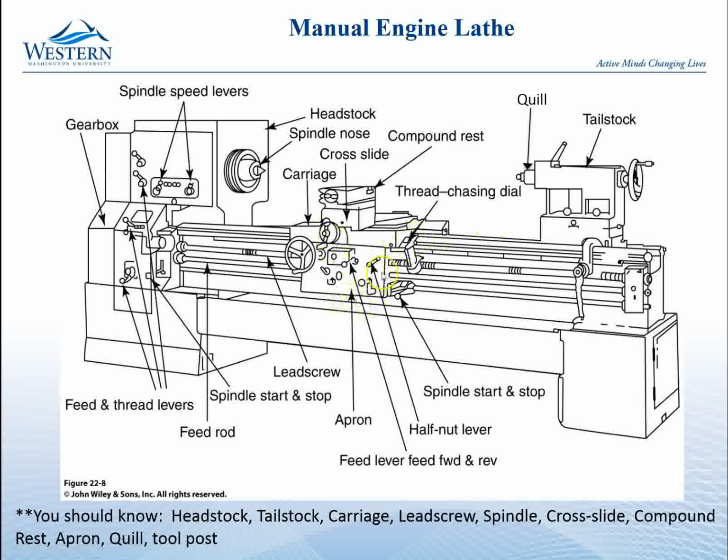Other parts of the machine. We have this part that travels along the axis. So if we think of the axes of the machine tool, we said for a mill, the axis that moves along the axis of rotation was Z, and so that is the same in a lathe. This is the Z axis back and forth. And so the part that moves along the Z axis is the carriage. That's this whole big thing.